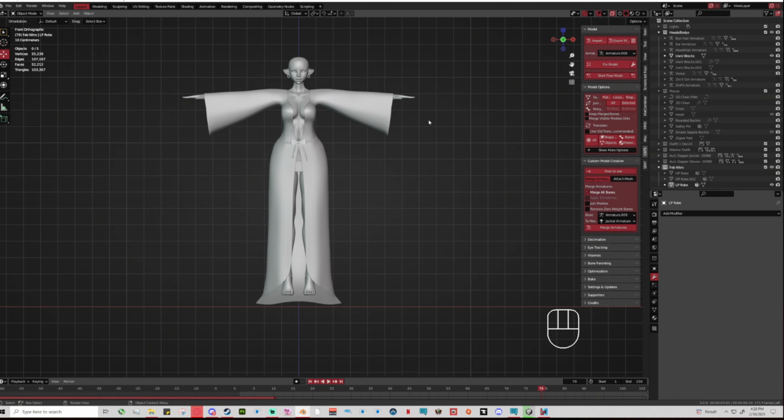So yeah, I'm probably gonna go through and redo the UV map and see if I can get it to be a little bit cleaner, but that's kind of just the gist, which is what I wanted to show you guys. So go through, think about where the seams are going to be, mark those edges, and then hit mark seam, and then you can go into your UV edit and I personally recommend doing the project from view first and then doing the pack islands and the average scale.